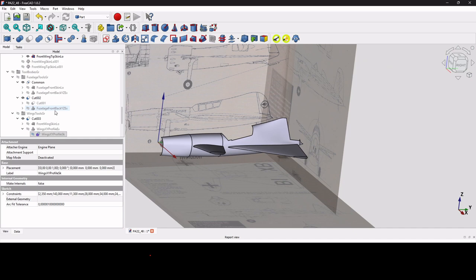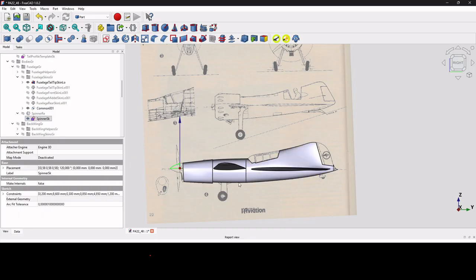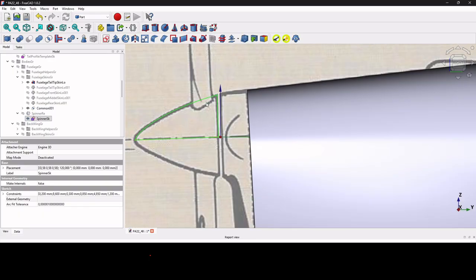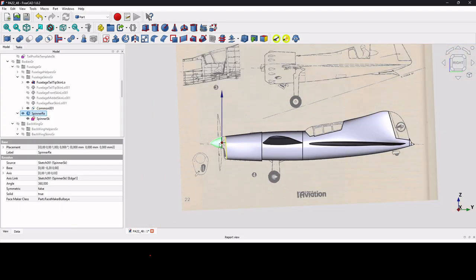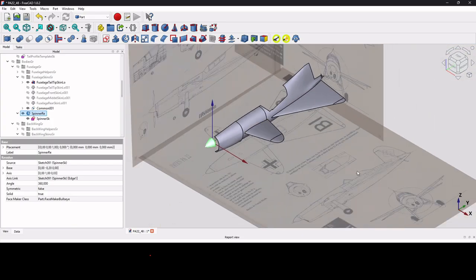So now it turns out also that I have done a little spinner, which is really this thing here, as a sketch in that, and you can see here that there is an angle, so that means the spinner is going a little bit downwards, okay, and then you do simply a revolve with respect to this axis, and you have that.